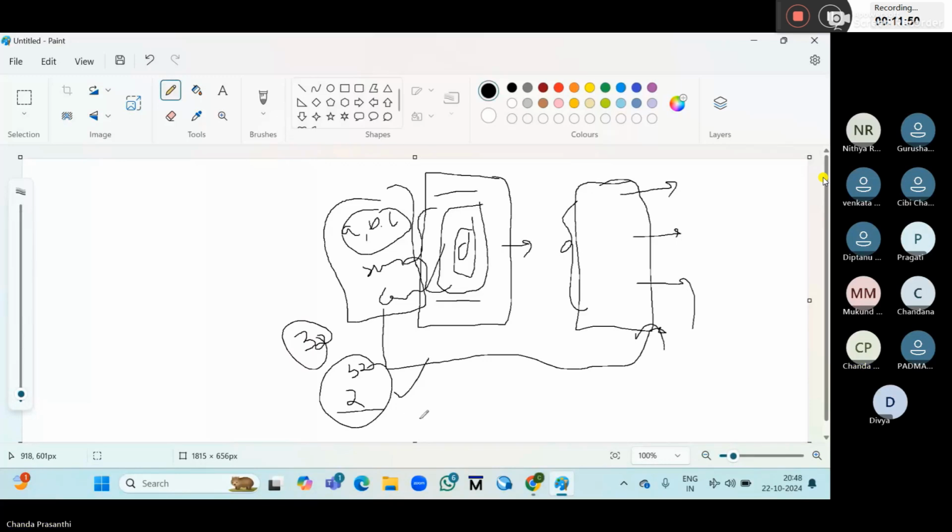So it is not easy to verify all the corner case scenarios or the main scenarios, short transactions, medium transactions or large transactions, whatever we divide into test cases. It's not easy to validate ourselves. We can do the verification, but we need to validate, right? We need to check whether we reached 100% verification or not, whether we covered all the cases or not. So for that purpose, we take coverage analysis.